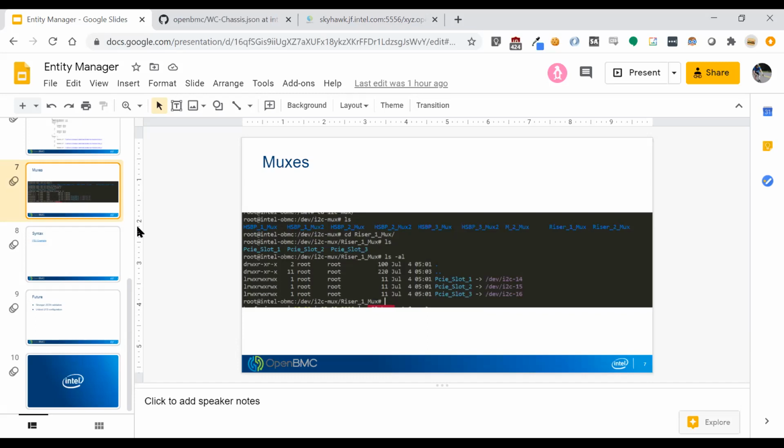And there are I2C devices next to the EEPROM, but also behind that mux. Okay. And the things behind the mux, how do you know that they're there? The EEPROM in front of the mux is on the same PCB as the mux. And so when you find the EEPROM, you know that there's the mux and devices behind it.